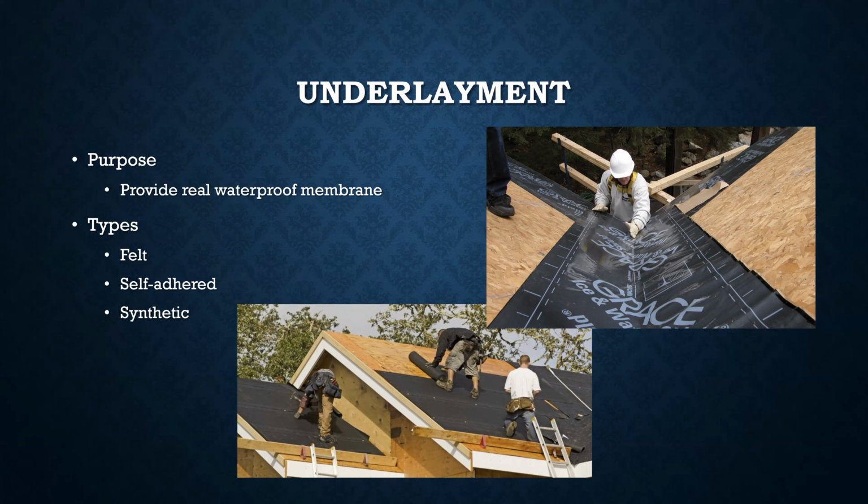There are multiple kinds, but there are special products. In the top right photo, you're seeing Grace Ice and Water Shield. That is designed to be a very good barrier against ice and water. They're putting it on the eaves and in the valleys because those are frequent leak areas, and they want to make sure there's not going to be any leaks. And it's a good idea to put it on your eaves because eaves is where ice damming happens. The valleys, it can happen as well.